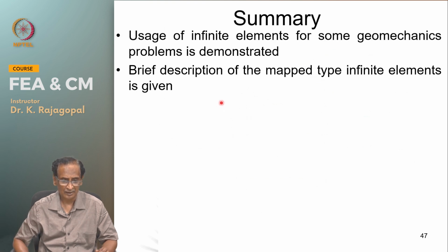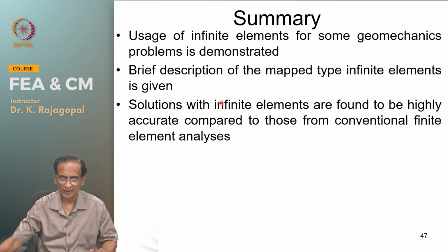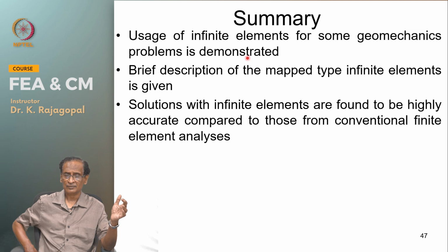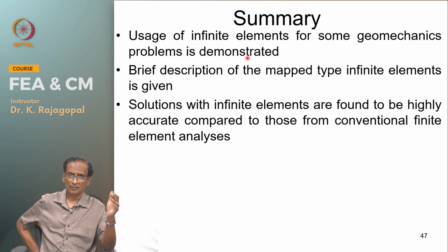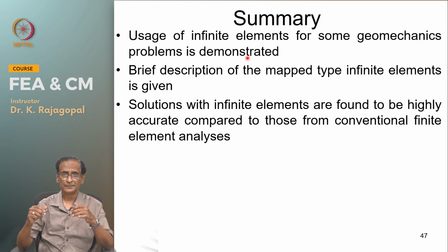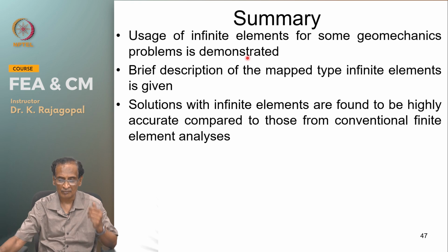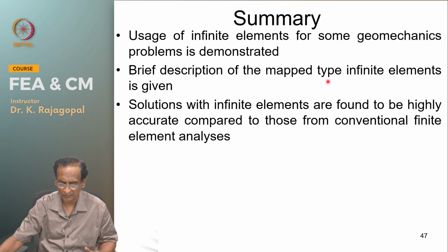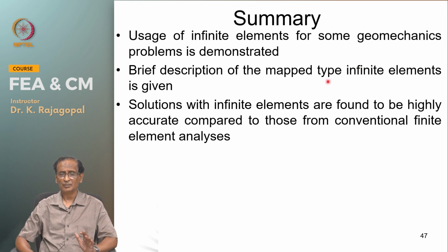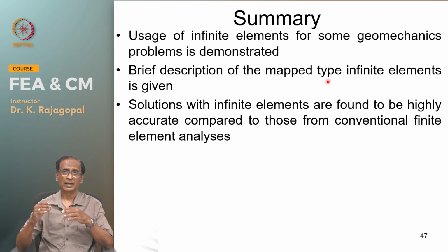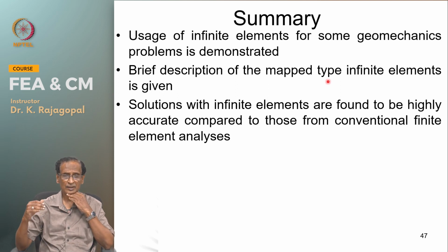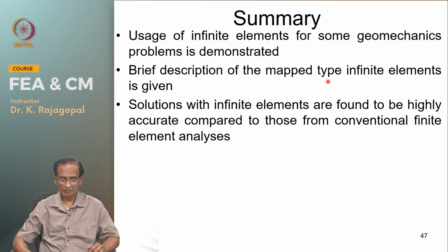So just to summarize, the use of infinite elements for some geomechanics problems is demonstrated. We have seen footing problems, circular footing, and then the wall footing or strip footing, and then we have seen pile foundations. And the mapped infinite elements are very similar to our isoparametric elements, except that they have singularity in their mapping functions, and they are highly accurate.